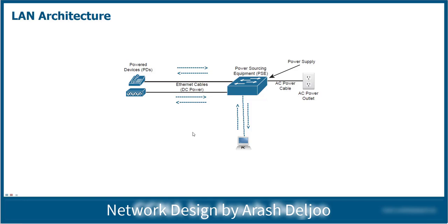Or maybe in some cases we have other solutions. For example, in some powered devices, when the device is off, the pin in and pin out are connected to each other. This means that the device is residing in a short circuit status. Because of that, if you send a little signal to the other side, you will receive the signal back, and this means that this is a powered device. Also, we have other options for detecting whether the next device is a powered device or not. This is not important for us.